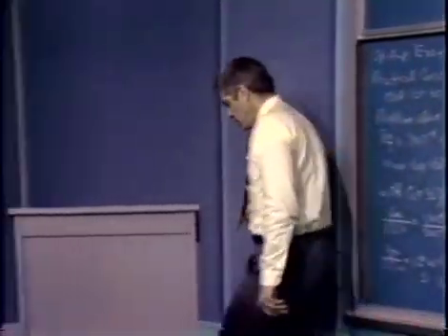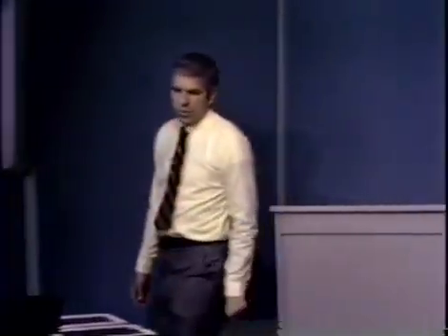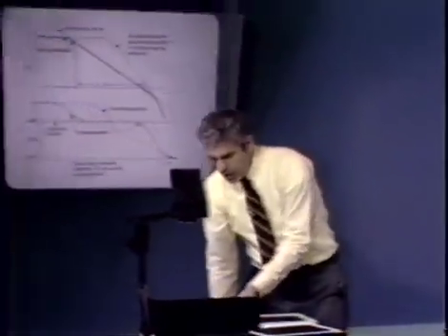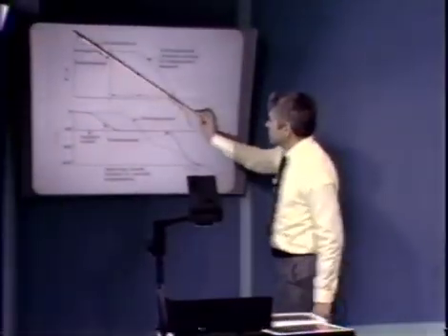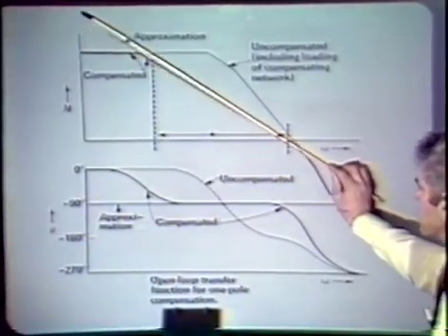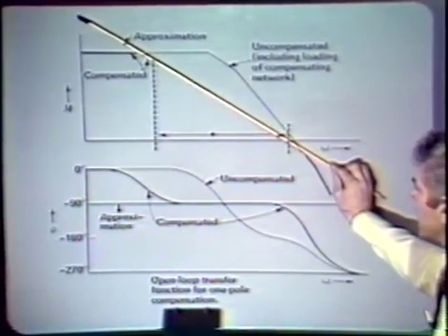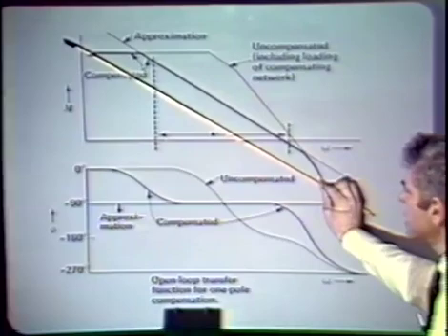We can again look at the effect of that on one of our earlier view graphs. This is the curve that is G sub m over 2 times C sub C S. As we change the value of C sub C to larger values, the curve moves down.